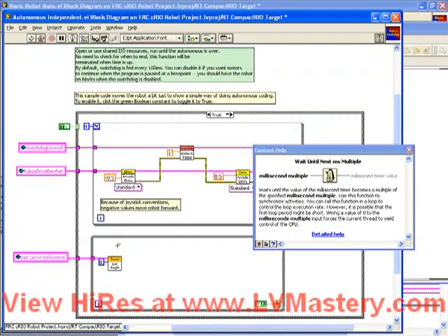The purpose of the Watchdog timer is to shut down your outputs, to basically go into a safe mode whenever the code locks up. And the way Watchdog timers work is you must feed a Watchdog periodically. If the Watchdog timer goes to 0 before it's been reset or fed, then it goes into the alarm state and the system will shut down. So we cannot put a simple LabVIEW-based delay in here because during that delay it will not be feeding the Watchdog. So that's why this function has been created.